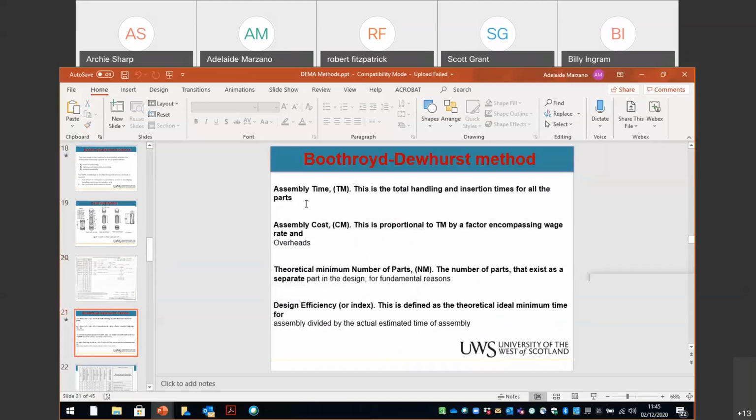For the assembly of the operation, you might have used the Lucas method, but you can also estimate a time for each operation. That's an estimation. You can use information from what is currently recorded in some cases, but if not, you need to have an estimation, if you are familiar with the operation.